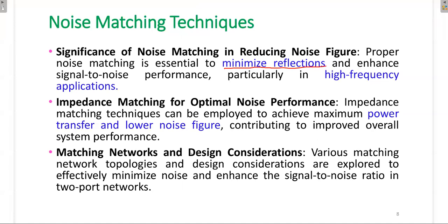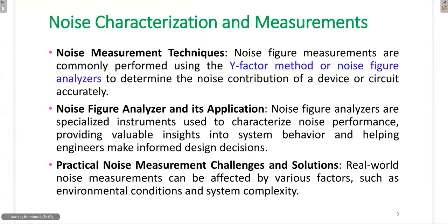Next, matching networks and design consideration. Various matching network topologies and design considerations are explored to effectively minimize the noise and finally to enhance the signal to noise ratio in the two-port network. Noise characterization and measurements. Noise measurement technique. Noise figure measurements are commonly performed using Y factor method or using noise figure analyzers to determine the noise contribution of the device or a circuit.